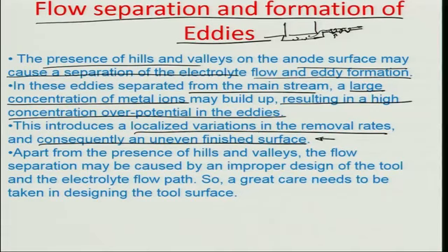Apart from the presence of hills and valleys, the flow separation may also be caused by an improper design of the tooling system and the electrolyte flow path, so there is a need for quite a bit of care for a designer to design the flow direction and the flow path of an electrolyte in a manner so that such problems don't happen.